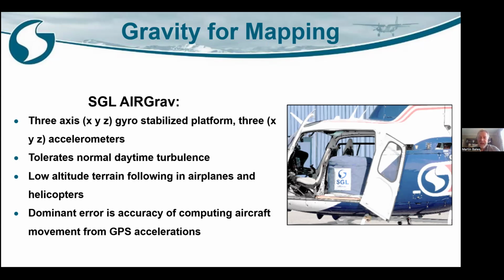It keeps itself flat relative to the ellipsoid of the Earth, which is a mathematical equivalent of what the surface of the Earth is, because it detects the rotation of the Earth and orients itself using gyros and orients itself perpendicular to that. That isn't perpendicular to the vertical gravity because that's often an equipotential surface, which is the geoid. So when we're measuring the vertical and horizontal components, that's how we can see what the geoid is because of it.